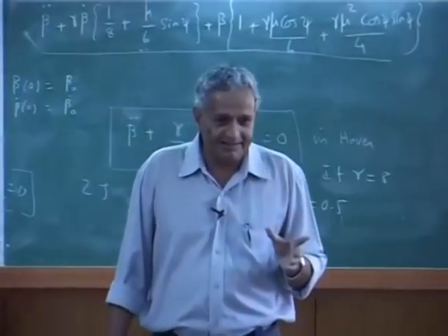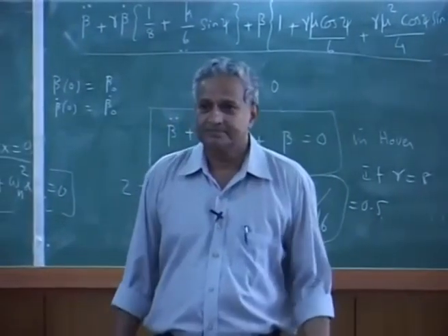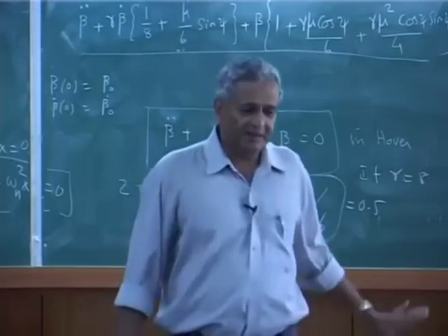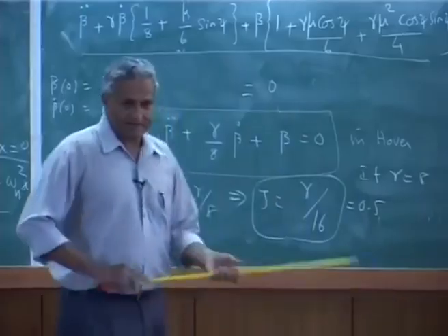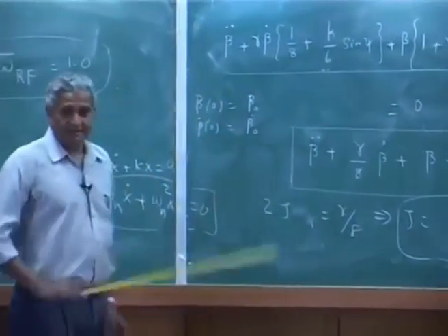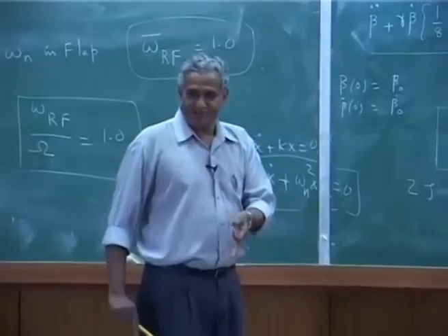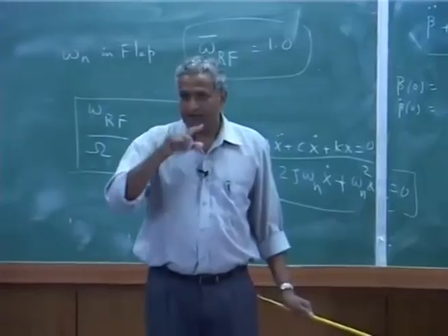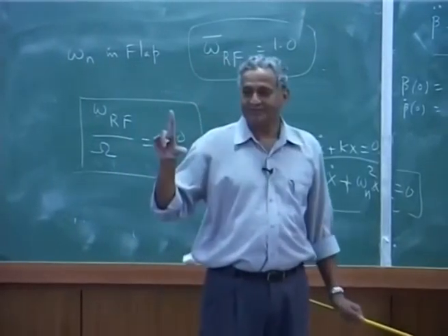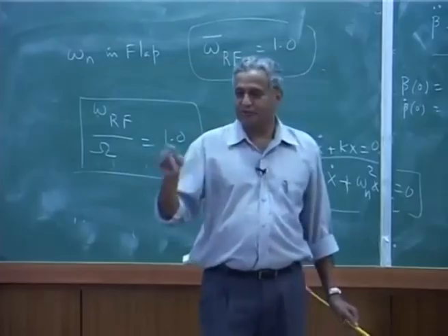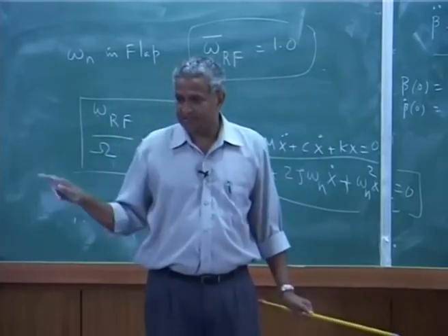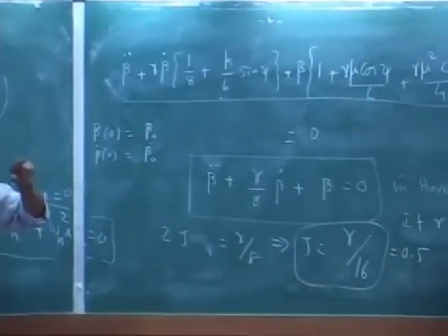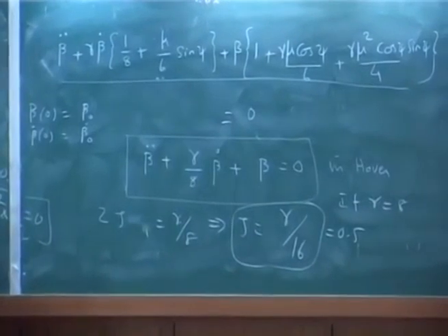That is why, in a helicopter blade, analyzing whether the system will be stable or not is something we will cover later. Right now, as a numerical problem, you can't write a closed-form solution like this. Get the solution numerically, and then plot it. Look at how the solution really looks for different values of mu. For small values of mu, the solution will converge immediately. Whereas for high values of mu, it will start oscillating, and then it may start diverging also.